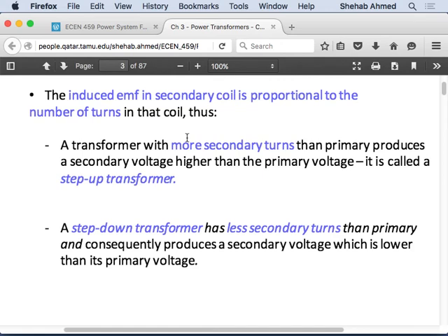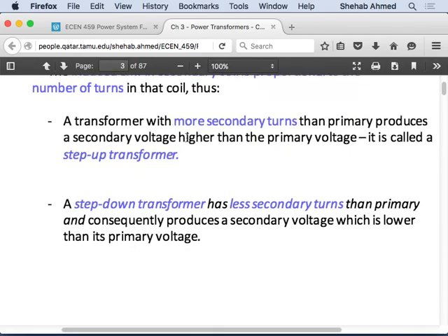But to operate at 4 volts and to operate at 8 volts, you need a certain number of turns as well. That's why in 438, when you were building the transformer in the 438 class, you used so many turns. Because at a certain frequency and operating at a certain voltage, you have to satisfy a turns ratio as well as a certain number of turns, right? And we will see that shortly.